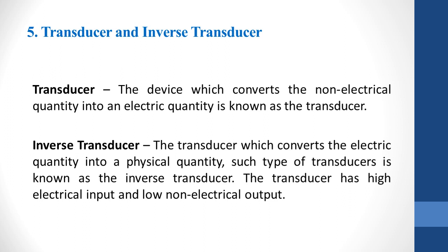If an electrical signal is given as an input to the crystal, it will vibrate. The thermocouple can also act as an inverse transducer. We all know about the working principle of the thermocouple. It works on the principle of the Seebeck effect when it is used as a temperature sensor and the output is an electrical signal. Suppose when an electrical signal is given to the thermocouple, what happens? It will generate a temperature difference between the cold junction and hot junction. So it acts as an inverse transducer.